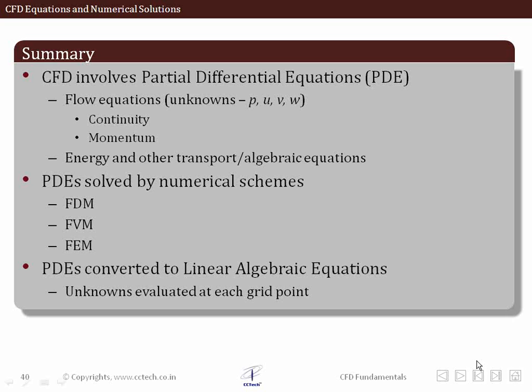Just to summarize the overall presentation which we have gone through, we saw how CFD primarily involves the solution of the partial differential equations which govern the flow phenomena. Continuity and momentum define the flow of any fluid, but additionally we can also include energy and other transport equations. And the numerical schemes that we have studied, the methods like finite difference, finite volume, or finite element method, we'll be dealing with the finite volume method in the next lecture in more detail.